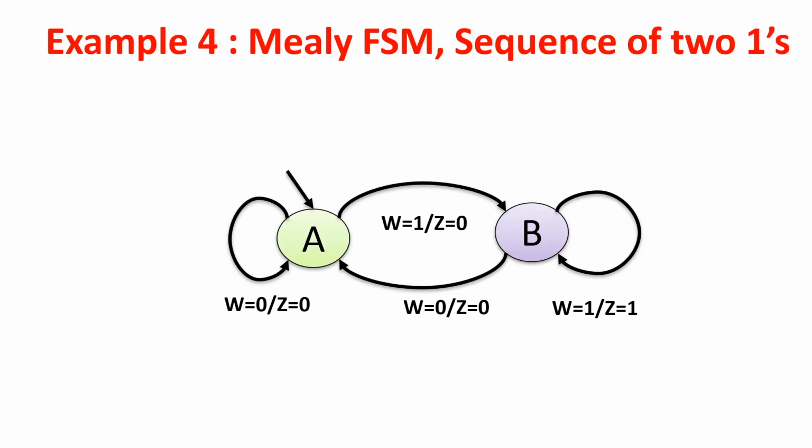The same thing, detecting a sequence of two 1s in the input, can be modeled using a Mealy FSM. This is the Mealy FSM. In this case, we can model the same thing using two states. We do not require three states.